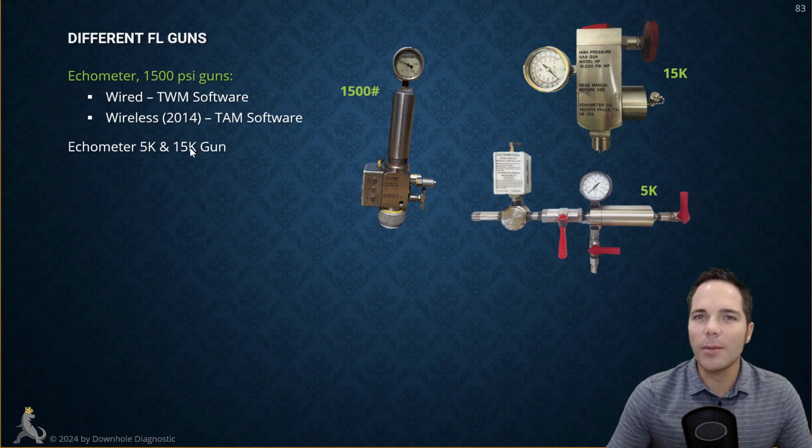They also have higher pressure guns though, so it's designed, you're not supposed to go above 1500 PSI with this particular gun. Remember, I just told you a story where I pressure tested it accidentally to 2200 PSI, and from my understanding, okay, don't hold me to this. Don't go above 1500 PSI in this gun. But from my understanding, they pressure test these guns to 3000 PSI. Okay, so anyways, you're not supposed to go above 1500 PSI. I have done that several times before. If a well's 1800 PSI, I'm okay with it. Again, open the valves slowly, be careful.